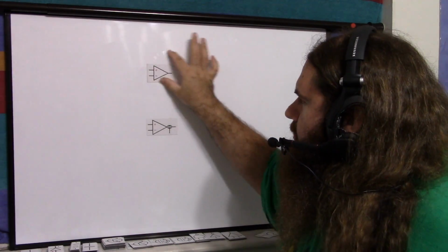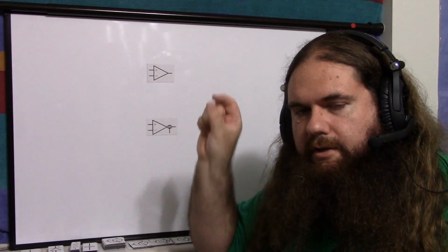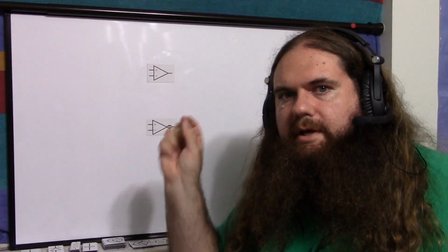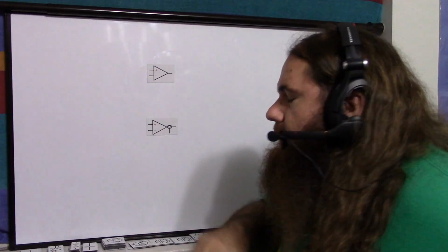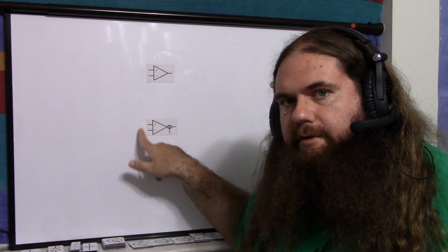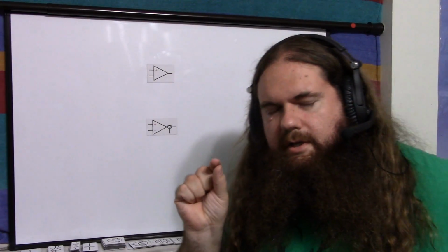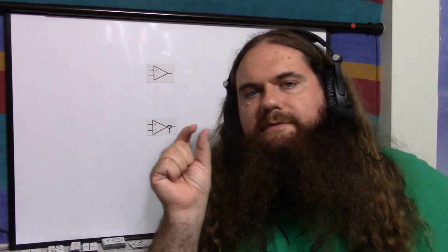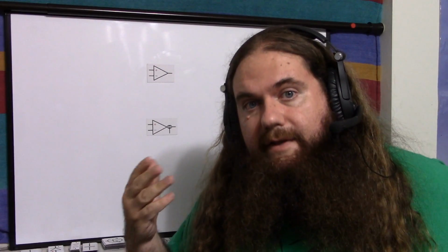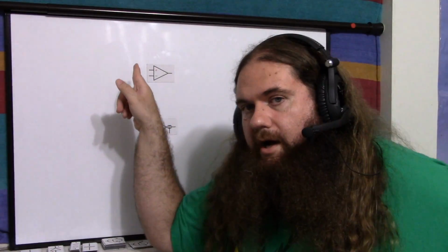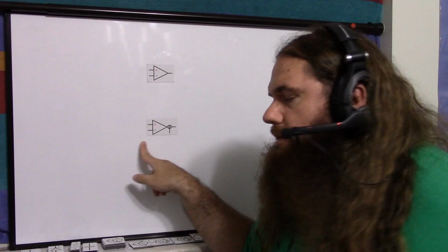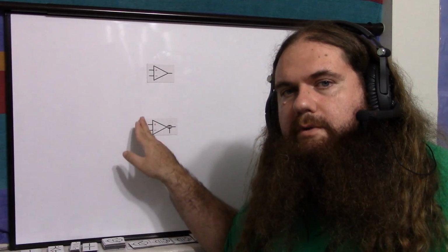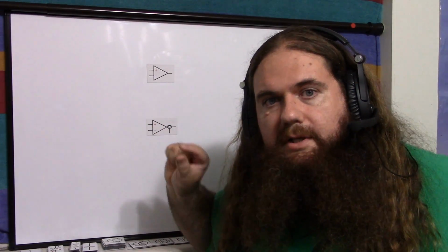For the op amp, you use feedback and configure the gain using your resistor, voltage divider, whatever. And it automatically sets the inputs to be very near zero. That's how it works. The OTA does not. You can supply whatever voltages here you want, but if the differential input is not close to zero, then it doesn't work right. That's the thing. The op amp automatically does this for you. Here, you have to set up a big old voltage divider or something, but the inputs you have to manually set to be 10 to 40 millivolts apart.